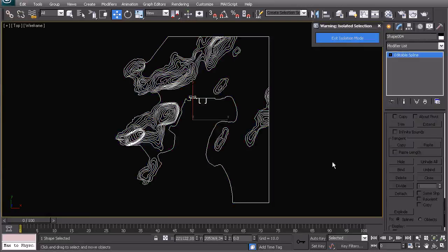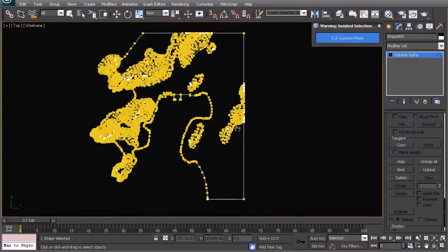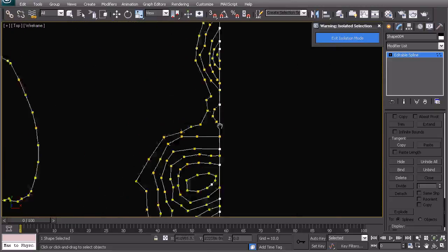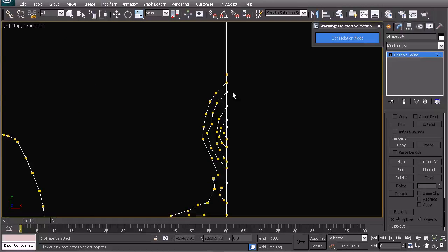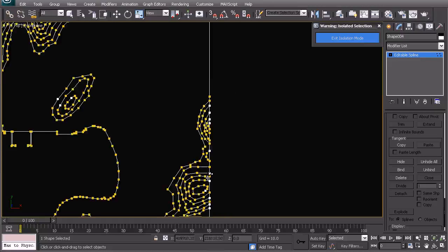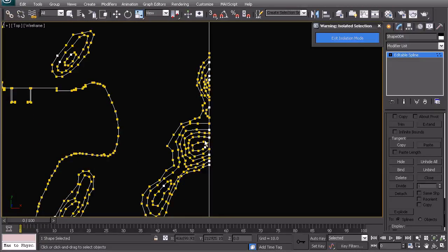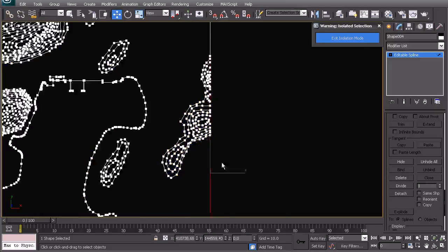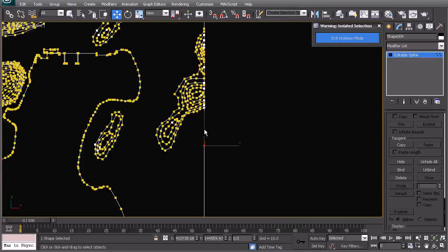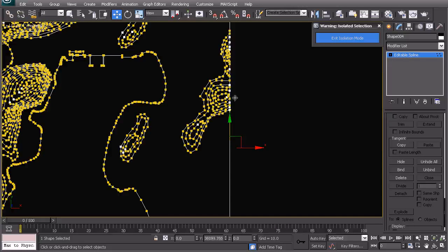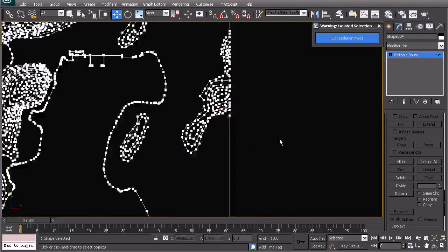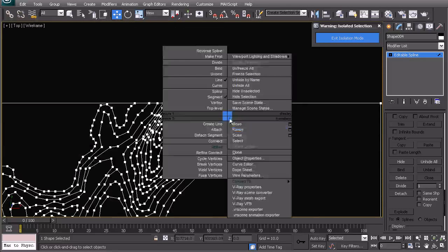And I'm also going to refine the edges a little bit so that we do not have the confusion of the line basically on the side here, which is saying 0, and right next to it we have, let's say, 200 meters. So that doesn't really work. So we will just do some editing here, create some vertices that we will then use to delete these lines.